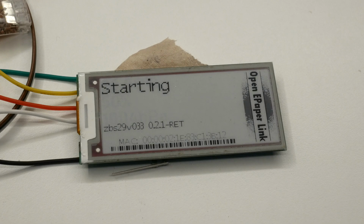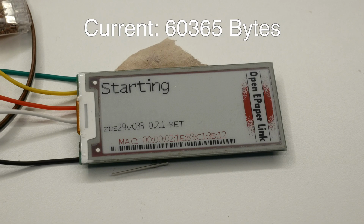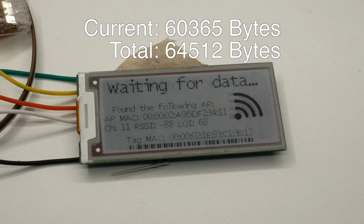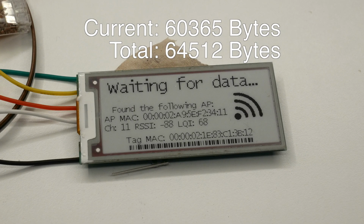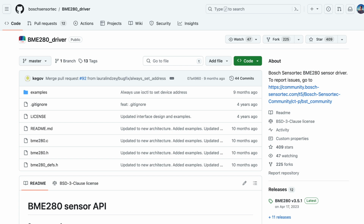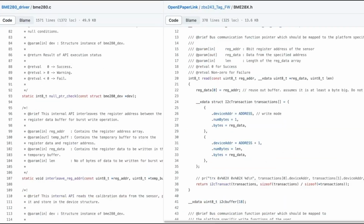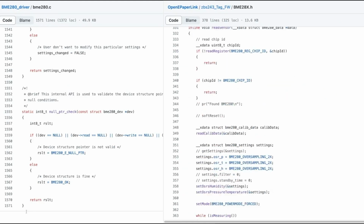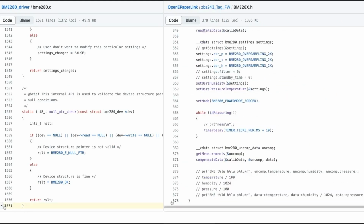To make matters worse, the current tag software already uses 60 kilobytes, which is almost 94% of the whole 64 kilobytes of available program memory. This gives us around 4 kilobytes to work with. Luckily, there were some features which could be disabled, reducing the binary to 55 kilobytes, giving us almost 9 kilobytes. I was hoping I could use the Bosch C library for reading the sensor, but that did not compile right out of the box for this architecture. After rewriting almost the whole library and removing as many unneeded functions as possible, I finally got it working. The code is now using 61 kilobytes, which is around 5 kilobytes more than the reduced binary.